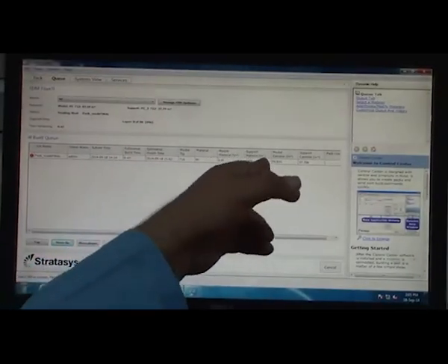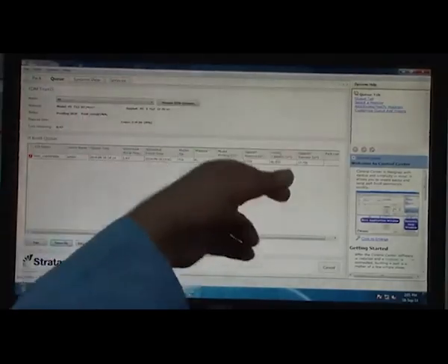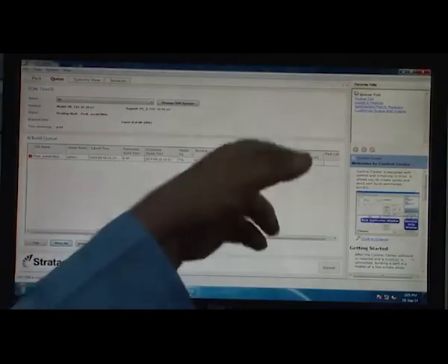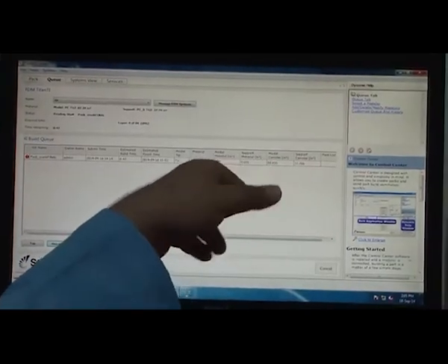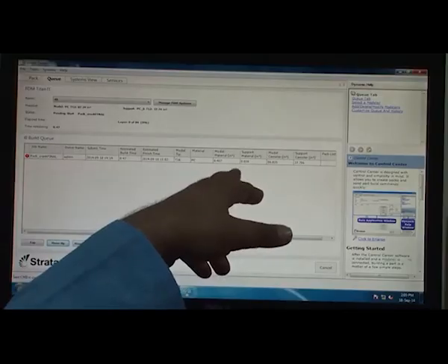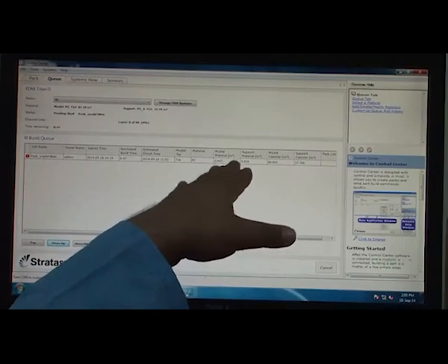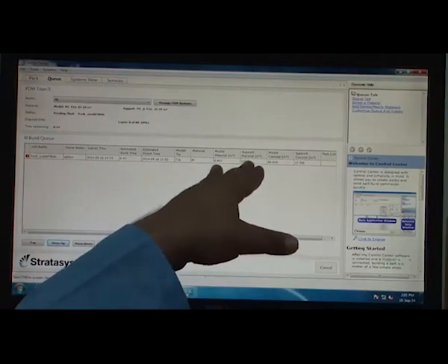You already saw the material confinement. I am going to illustrate this again, that there are these material canisters which hold the initial raw materials, those wires which you have to feed in. There is a calculation done by the machine itself which tells how much material is left, which is about 86 inches cube in the model canister. The support canister has a material of about 37 inches cube. The amount of model and support materials needed are also mentioned here as 0.407 inches cube and 0.038 inches cube. Typically you have to understand that these two which are needed should be lower than the material which is available. Once this condition is met, we are all set to do the machining operation, which we will see in the next illustration.